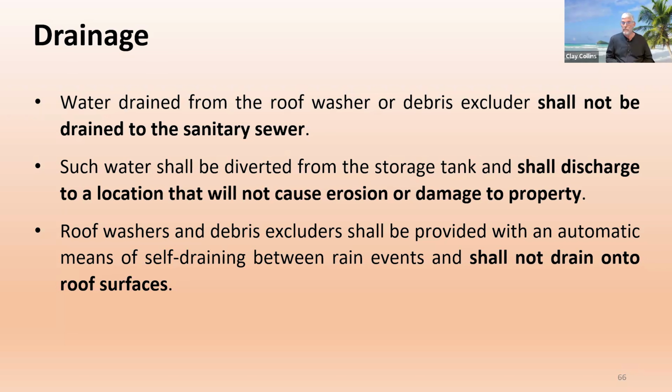Also, a lot of times you'll see gutters all the way around the lower eave, but you might have a second floor where the runoff from that second floor falls down onto a porch, patio, or lower roof. And over time, you can see the erosion. It just tears the granule, the aggregate off of that shingle. And now you've got a bare shingle that you've cost a lot of life. But you need to discharge all the water so it doesn't cause problems.